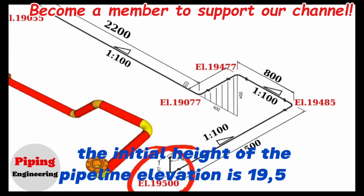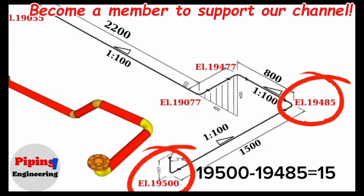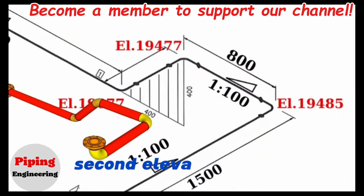Here, the initial height 19,500 mm minus the second height 19,485 mm equals 15 mm. With this method we can calculate the difference of the levels in the second and third turns. Second elevation 19,485 mm minus third elevation 19,477 mm equals 8 mm.